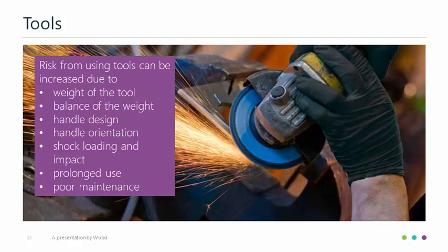Along with this, we have linked maintenance programs so that tools are recalled and reviewed on a regular basis, as well as when issues are reported with them. Strict adherence to the duration of tool use is also followed, with various means of recording usage times used, results reviewed weekly, and corrective actions, including corrective conversations, had as necessary. Our aim is to keep hand-arm vibration exposure as low as reasonably practicable.